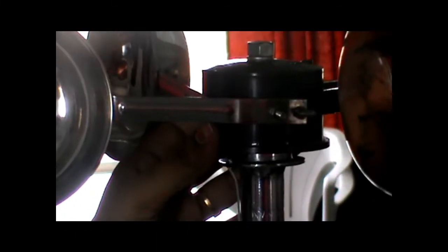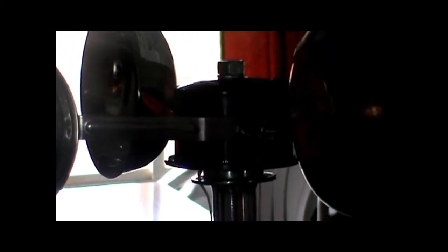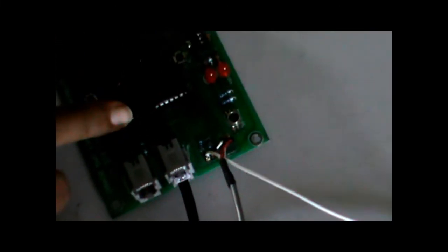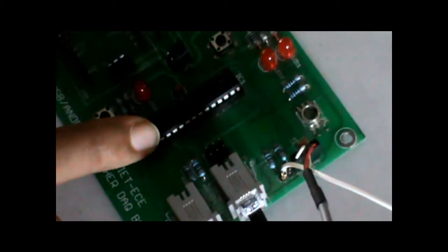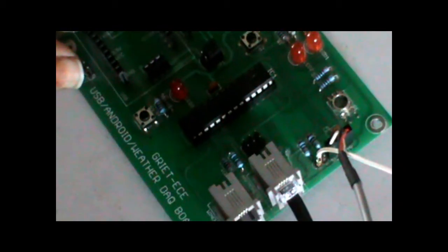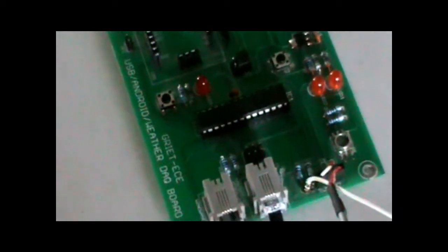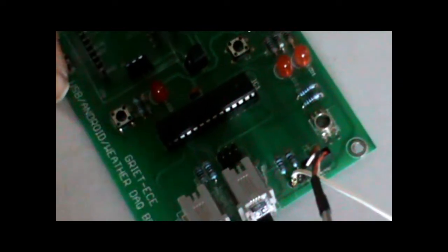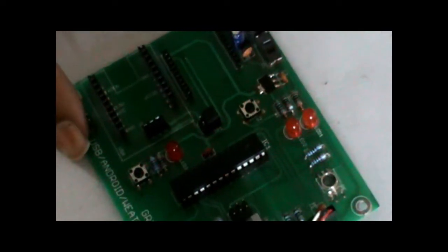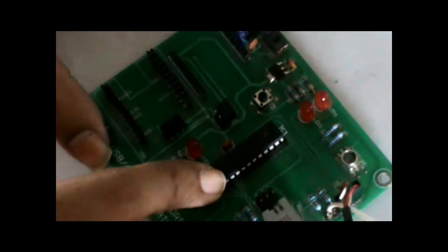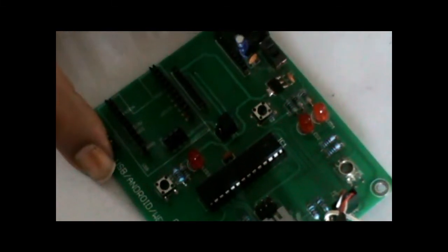The stator part has one reed switch and the rotor part has a magnet. Whenever this magnet comes over the reed switch, the reed switch gets shorted and a high to low pulse comes over here. This should be given as an interrupt to the microcontroller. We will write the ISR in such a way that we increment a variable inside the function. One of the timers is to be set in order to give a particular time, like 5 seconds or 10 seconds, for how many seconds we have to read those counts.